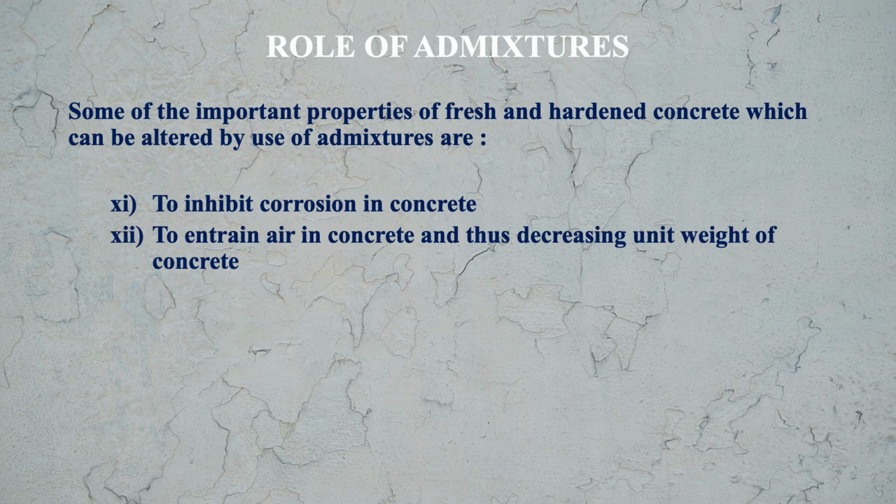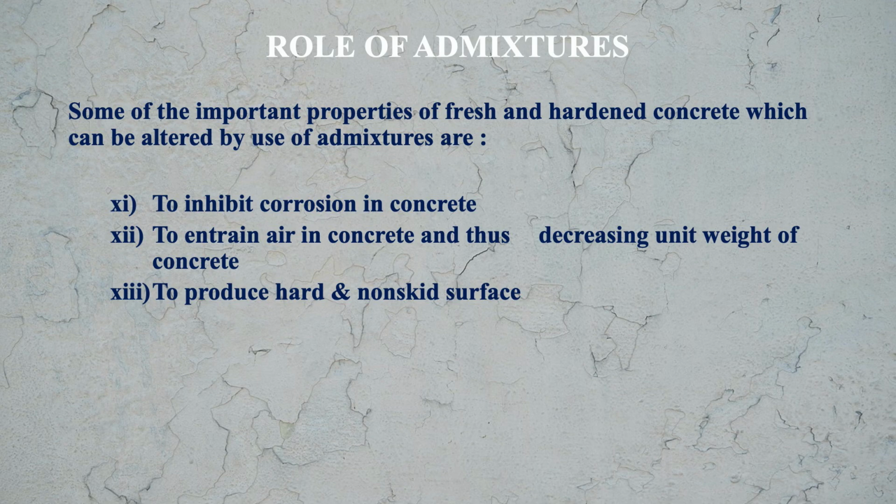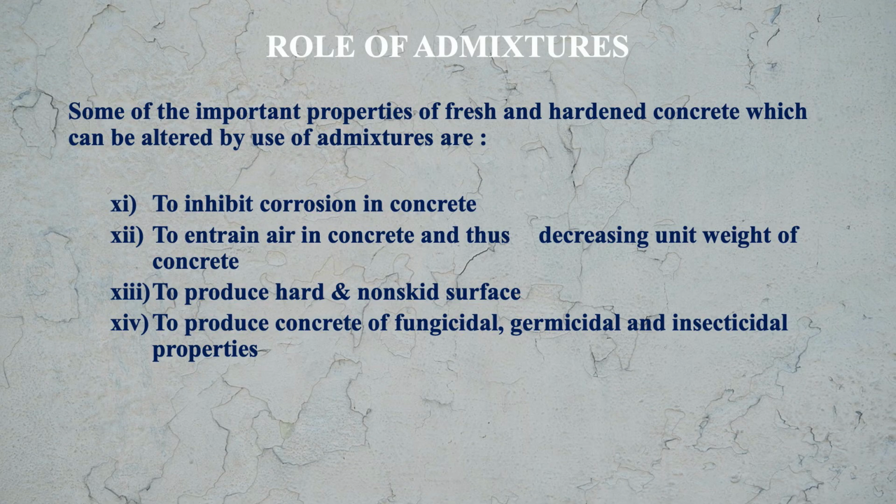We also use admixtures to entrain air in concrete and thus decrease the unit weight of concrete, because air entrained concrete will have a lesser unit weight. Also, we use the admixtures to produce hard and non-skid surfaces. We want the surface hard and non-skid. To produce concrete of fungicidal, germicidal and insecticidal properties, for this purpose also we use the admixtures in concrete.